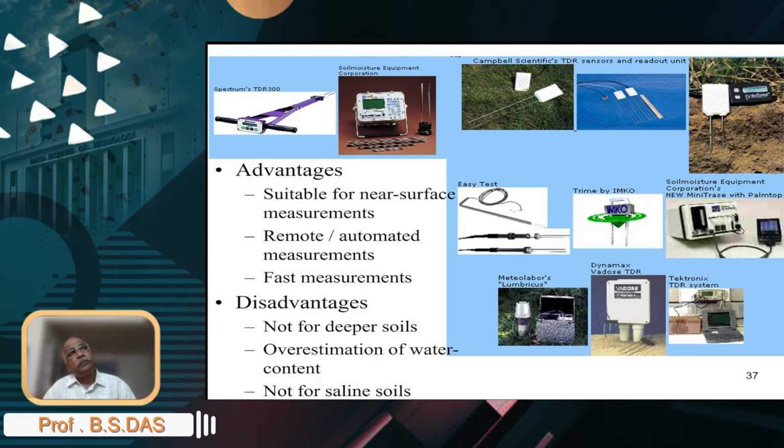The frequencies operating in these TDR probes are at about 3 to 16 gigahertz range, because that's where the differences in soil textures go away, and so you can just use a single calibration curve, like a factory installed calibration curve. Measurements are fast because of the electrical nature.